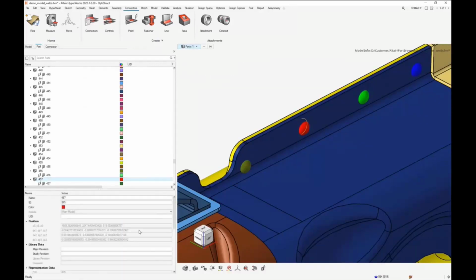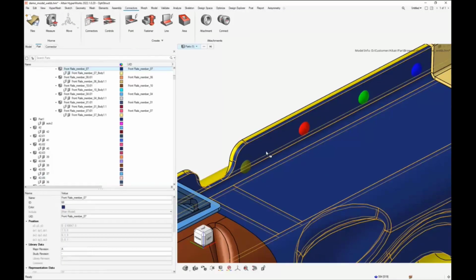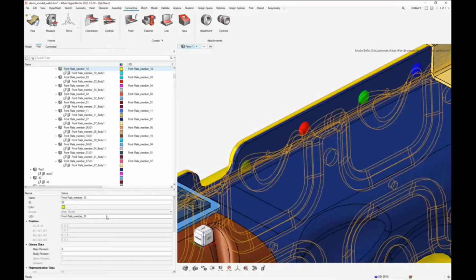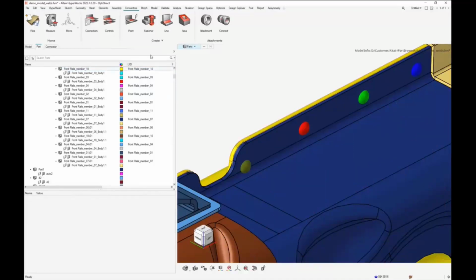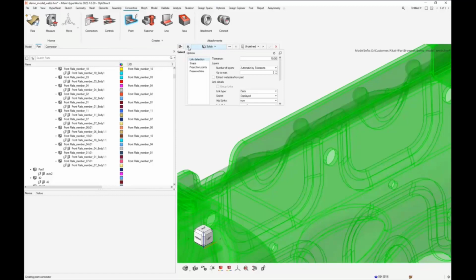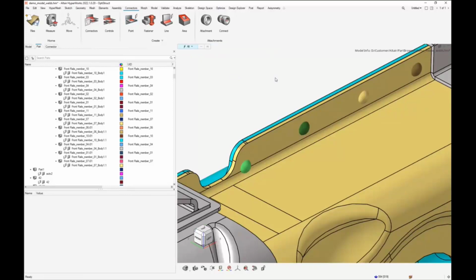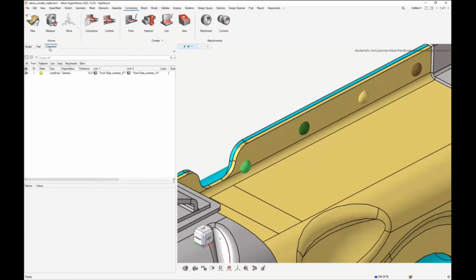So what does that look like in action? In this case here, I've got a particular solid geometry. If I scroll down, it tells me connected part 1 and connected part 2. It tells me the connector type, and it can tell me the ISO process type or the connection methodology. So in this case, I know that the connected part 1 and 2 are pointing to UIDs. So I can go into my hamburger menu, click on extract metadata from part. I know I'm looking for the UID. I know I'm looking for an exact match. I can select the solid.